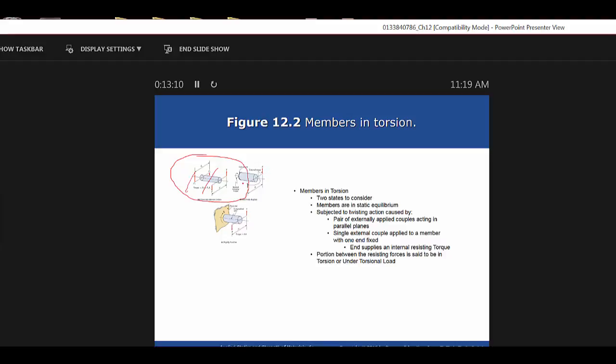Okay, and do they have that? Did they show that there? Yeah. Over here they say the torque is equal to FB, and it's just the force times the distance of one of those couples. Okay? So the force times the distance of just one of the two couples. So when you cut it in half, you're taking care of that, aren't you?